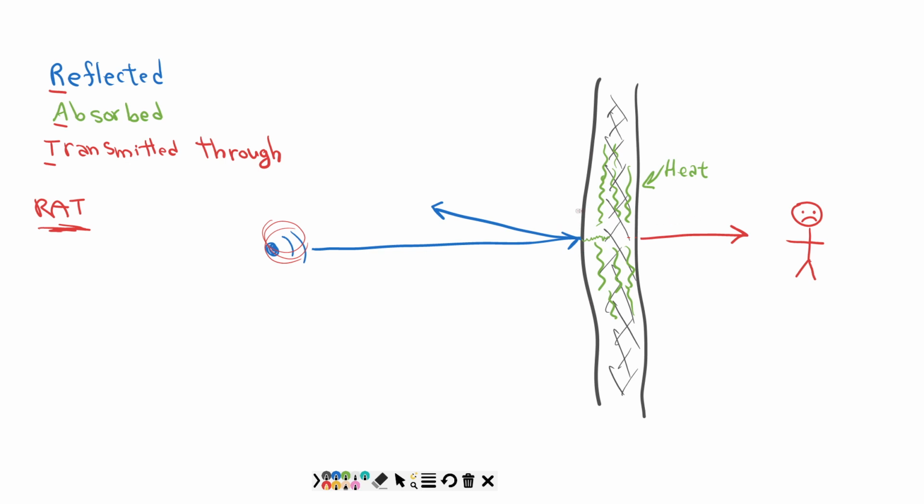And these characteristics, sound being reflected or absorbed or being transmitted through, will depend not just on the material, the structure itself, and also things like frequency. In other words, I can have a material that's really absorptive at 5 kilohertz and is not very absorptive at all at 100 hertz.